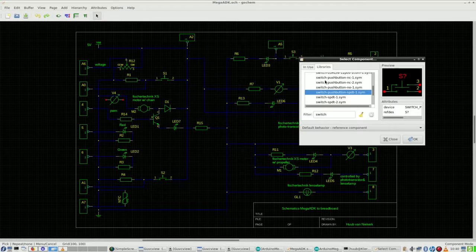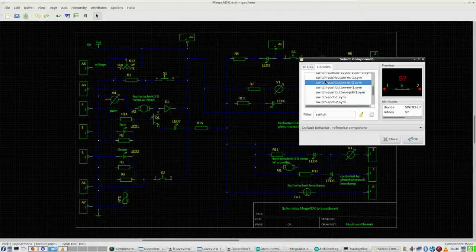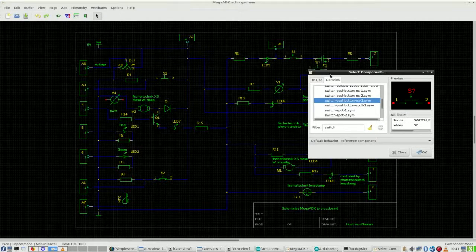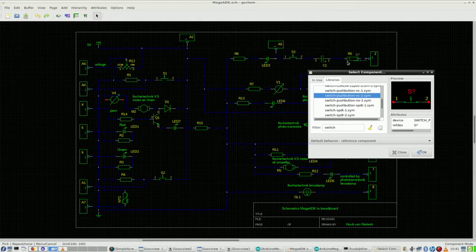See, you have here a break contact. This is a break contact. It is default on, you press on it and you break the contact. This is a make contact, which is default not connected. You push it, you press on it, and the contact is being made. So the current situation will be logical in this situation.